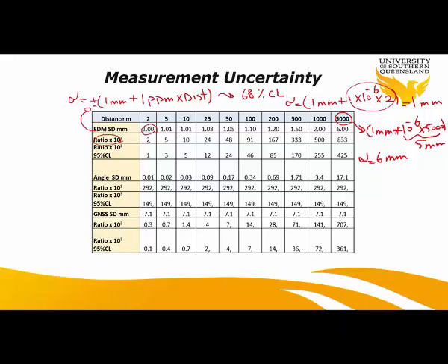This is the ratio, so it's basically the part per million this bit here, and this is the ratio at 95% confidence level. We all know that it's roughly divided by 2 or divided by 1.96. Same thing for the angle. Angle pointing is 0.5 second of arc for one pointing, and is inversely proportional to the distance. So as we point further to the object in 5 kilometers, you're never going to get the same accuracy as at 2 meters, so it's getting worse.